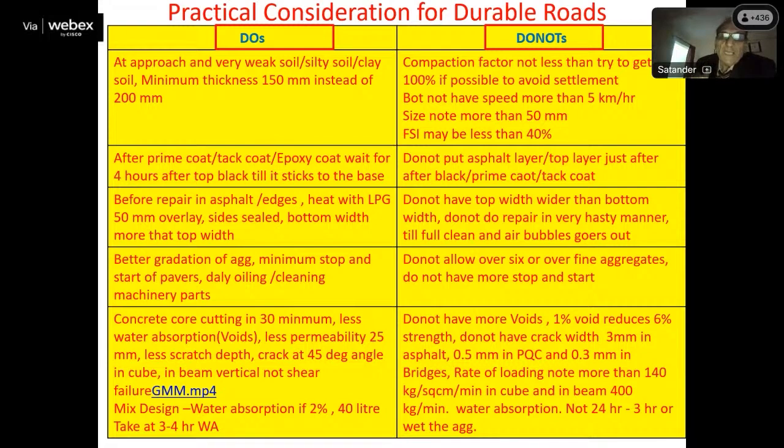If you go for a lower layer, any undulation in the lower layer, the ground level, 90% people, if you do proof rolling, you will 100% get very good riding quality. Many people have a thinking in their mind, sir, I am having a very good paver, we are having a sensor, sir, it will give uniform thickness. No, that idea is wrong. Whenever there is undulation in the ground level, in each layer you will find undulation.